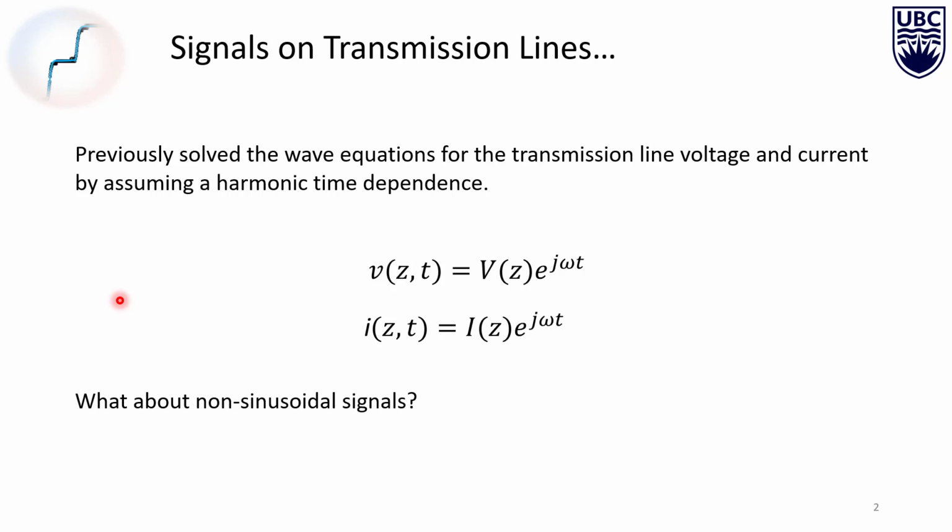what we talked about in the lectures when we were discussing transmission lines is thinking of the transmission line as a cascaded series of these LC branches, so an inductance per unit length and a capacitance per unit length. We had these branches follow each other one after another. We isolated one of those branches and analyzed it, and we eventually ended up at the wave equation for both the voltage and current of the transmission line. That wave equation was a partial differential equation that involved both position and time.